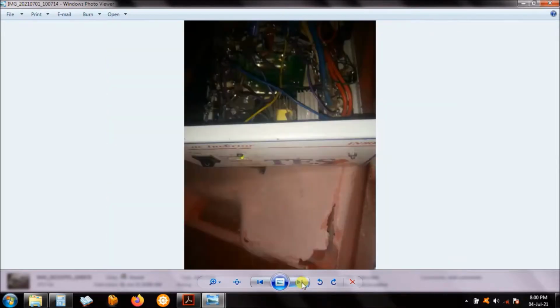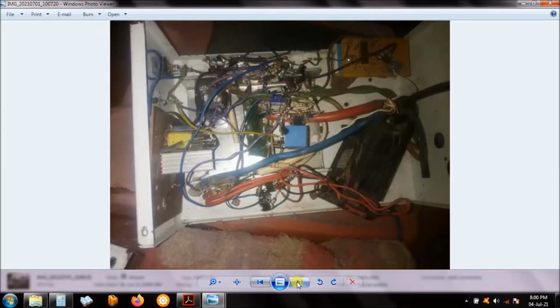Okay, the fan there, and in the enclosure, this used to be an inverter enclosure, a TES inverter, South African made inverter. Right, then I took out the transformer and the circuit for the inverter, used them somewhere on my inverters that I built, and then the circuit for the solar charge controller, I put it in there. Right, yeah, this is almost like the whole circuit together. This is the TL494 I see here. This board is driving these MOSFETs here.